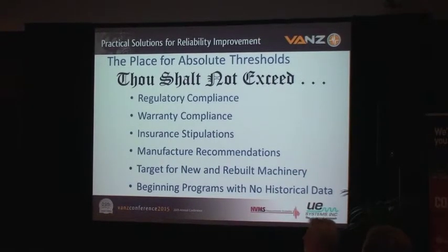We talk about manufacturer recommendations. I think absolute thresholds are good if you go back to the original intent of the original IRD severity charts. It's a great target for new, rebuilt, recently maintained, restored to service machinery. And I'm a firm believer that there is value in an absolute value threshold with a new program where you don't have any experience on a particular machine. I mean, you've got to start somewhere. You've got to have some threshold of concern.